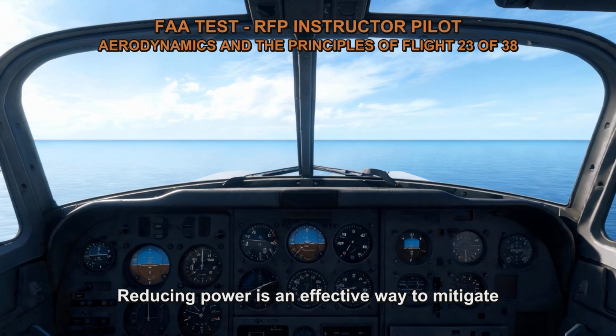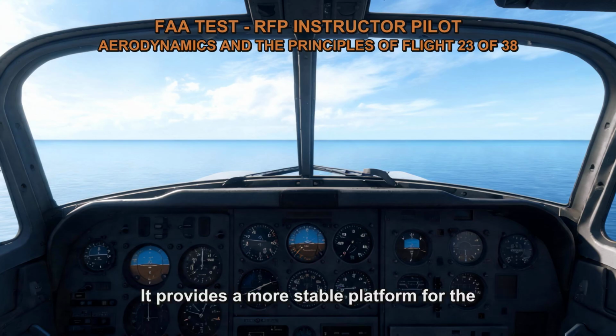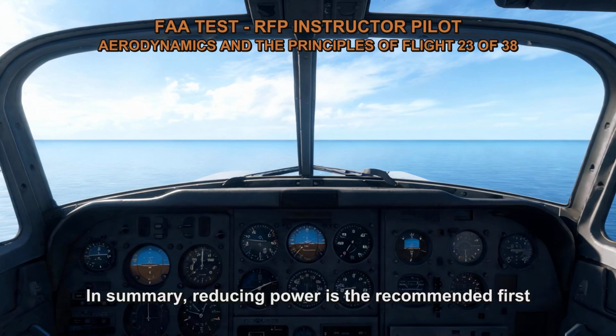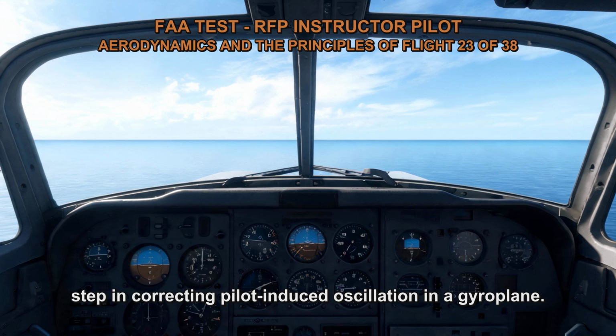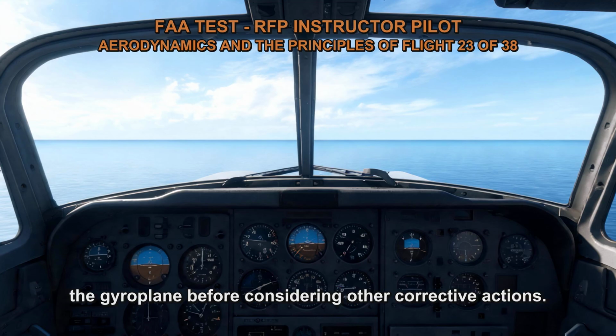Reducing power is an effective way to mitigate the oscillations and regain control of the gyroplane. It provides a more stable platform for the pilot to assess the situation and make further corrective actions if necessary. In summary, reducing power is the recommended first step in correcting pilot-induced oscillation in a gyroplane. It helps to decrease the energy input and allows the pilot to regain control and stabilize the gyroplane before considering other corrective actions.